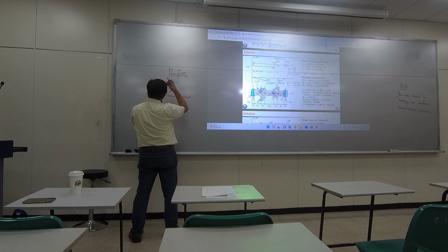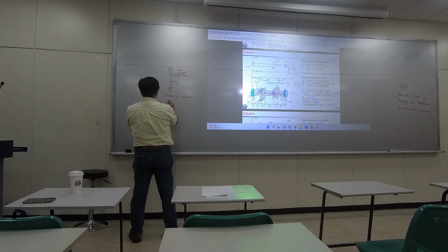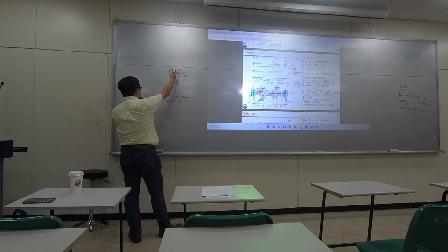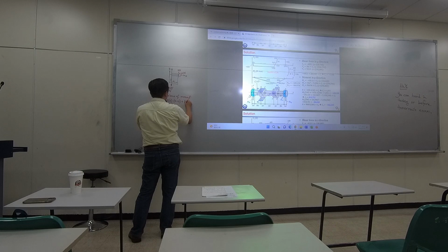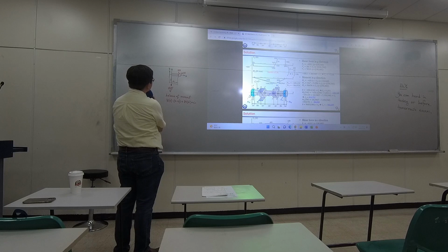If you do use a balance of moment and you have a center point right here at A, then you will be having V of x times this distance. So that would be x minus 10, going counterclockwise in my drawing. And this M is also counterclockwise, so plus Mx equals 0. Okay, so I would need balance of force as well.